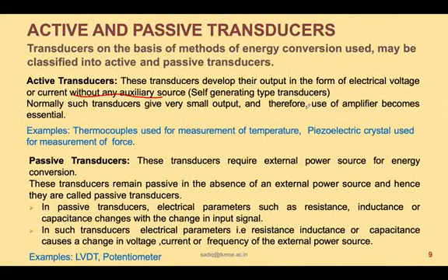We will give an example like piezoelectric crystals, where if a pressure is applied, the crystal will generate charges, and the charges will be of the order of picocoulombs, 10 raised to minus 12. Even in the case of barium titanate, it develops around 250 picocoulombs only per Newton load. That means such a very small charge, if it is to be utilized for sensing purpose or any other application, has to be amplified. So amplifiers are used along with the piezoelectric crystal.